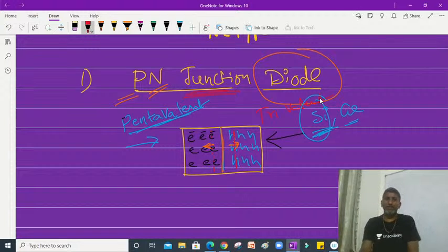When I say this is electron majority, this is the n-type semiconductor, and this is the p-type semiconductor. Now electrons move away from the positive charge, and holes repel from the negative charge of the n-type material. So a charge-free region is going to form. This is said to be the depletion layer. Depletion means making it empty. It is the depletion region or layer.